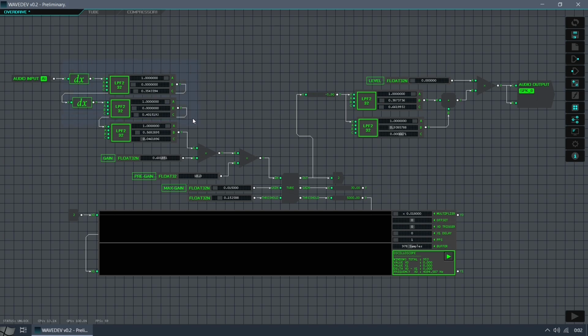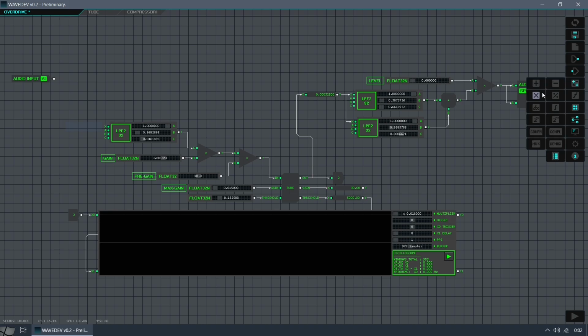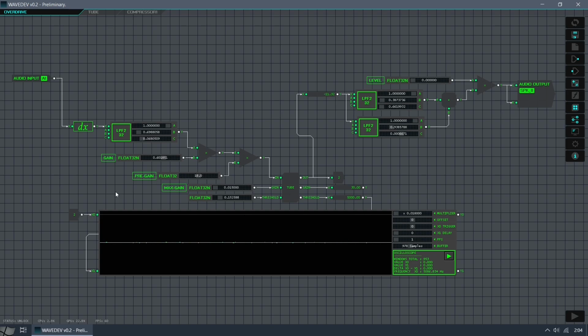We no longer need these two high-pass filters. We will keep the most important one, although we will convert it to its high-pass version. I'll use a normalization frequency of around 1.8 kHz. Later, you can try other filters here like a single high-pass filter or band-pass filter.